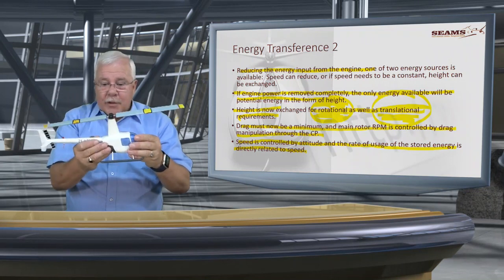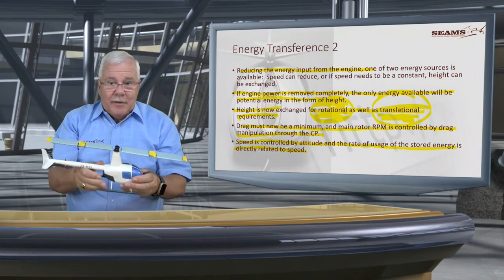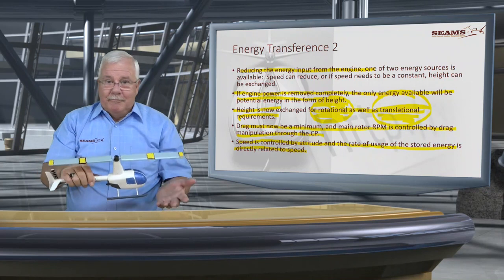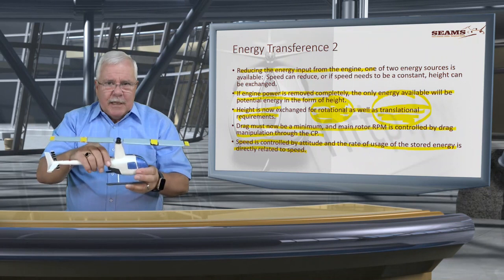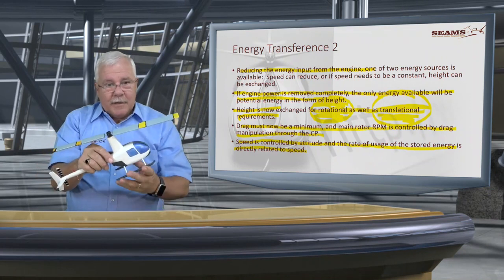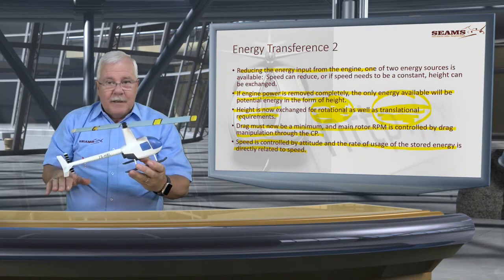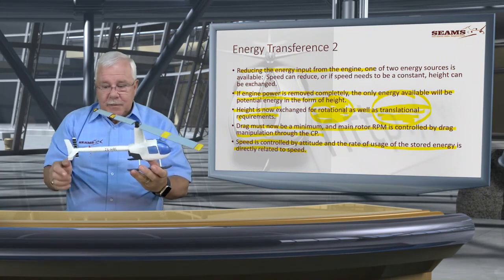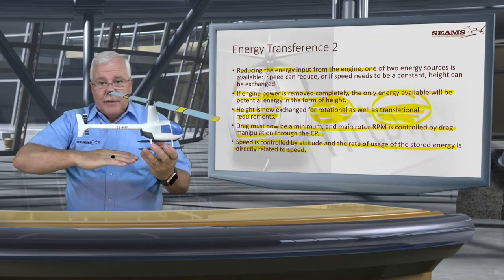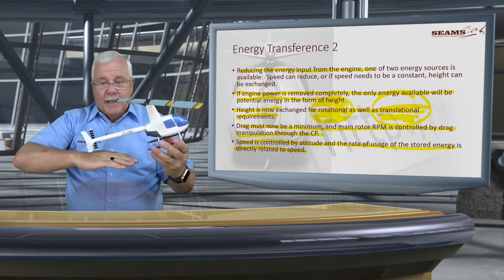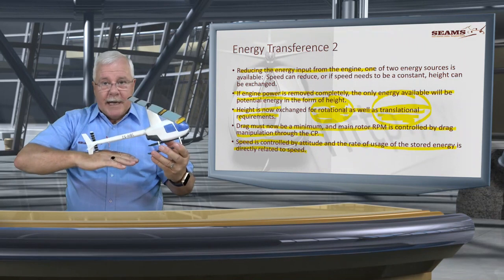But now, on the other hand, if you have got no flare effect left, you've got no more energy left, you've used up everything, then there's no more height to exchange. And the one thing that we must ensure at the end of the day, when we flare the aircraft close to the ground, is that there must still be a distance between the aircraft's tail and the ground, because, just listen to this, if this is the ground and you flare too late and you put the tail in, the speed at which you put the tail in is the speed of the accident.